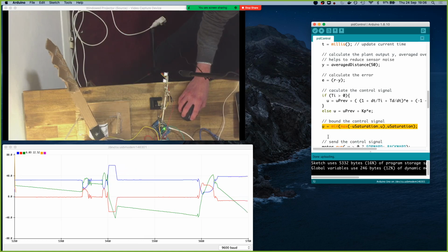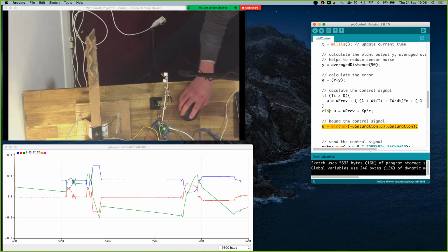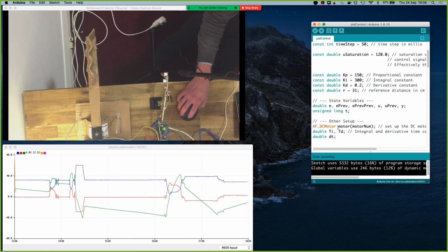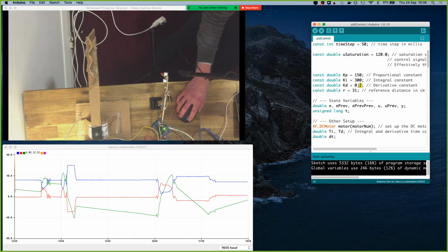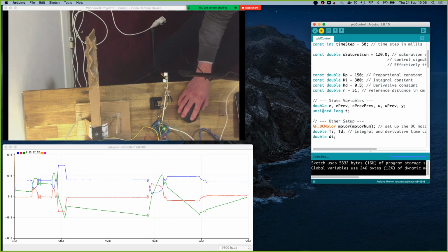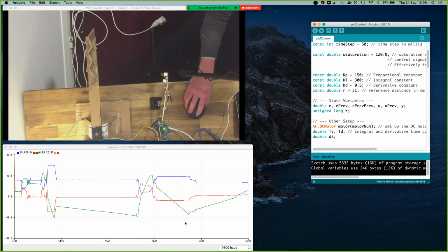Interesting. I mean, the control scheme that's here at the moment is actually reasonable. It's one of the most pleasing ones that I've got so far. I'm going to bump up this KD term and see what happens. It recovers within 1 or 2 oscillations and basically hits that equilibrium. This can be a little bit misleading. You might look at this and wonder what's happening.